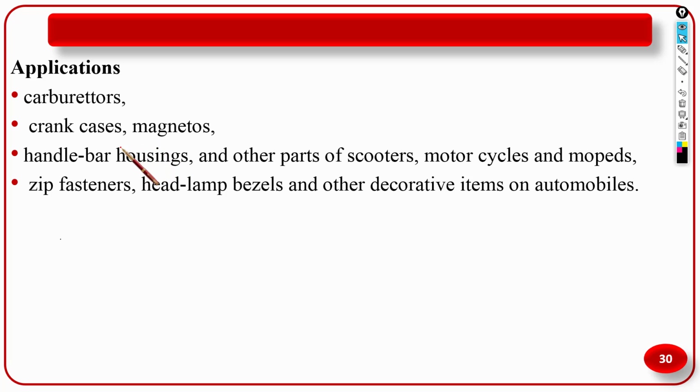They are basically made with die casting because it is much faster. Any material which is produced in a large quantity, first of all, that is very important. Like jeep fasteners. These are produced in lakhs and lakhs of quantities, so die casting is best for them.